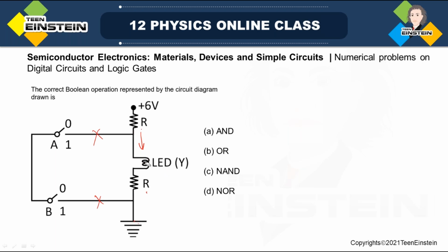And look here, so these are the input switches A1 and B1. So when these switches are closed like this, if this circuit is a closed circuit, then what will happen? Then current will actually flow through this and bypass the LED or this path. Then current will be 0 in this path, and through this path the whole current will flow, because this is simply a conducting wire.